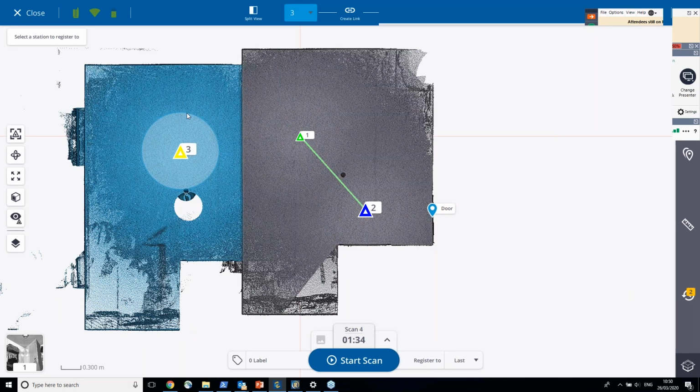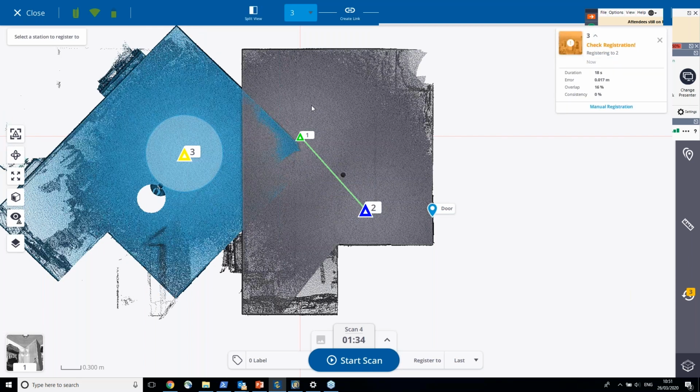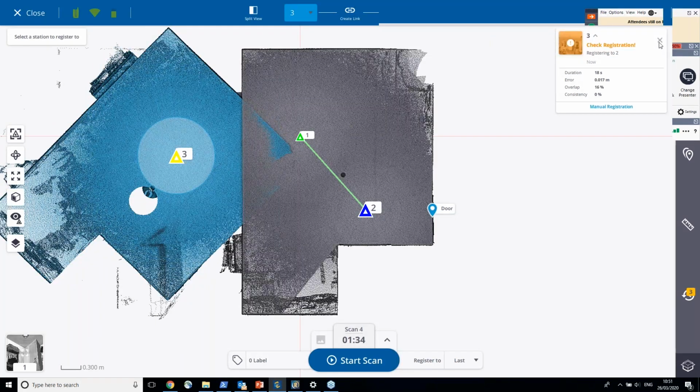The most important thing to fix the scan in perspective is that you get the orientation correct. So for example, if I, for whatever reason, got the scan in like this, and then I try to register, it will most likely fail. This is a very small room I'm sitting in, so it might be that, but in most cases it should fail doing that. It didn't really do it properly.